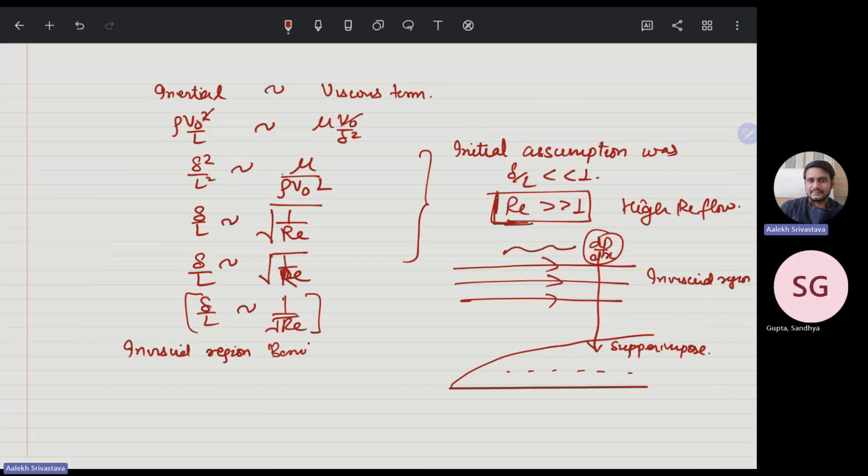The Bernoulli equation says P plus half rho V square plus gz is equal to constant. If I take the derivative with respect to x, it will be rho Vc dVc by dx equal to 0. You know the velocity is not changing along the x direction because it's a flow over a flat plate, so no area is changing, therefore no velocity is changing.